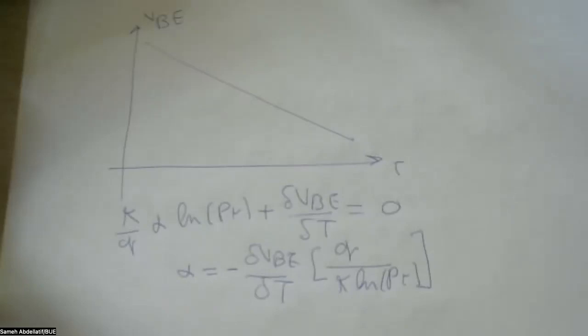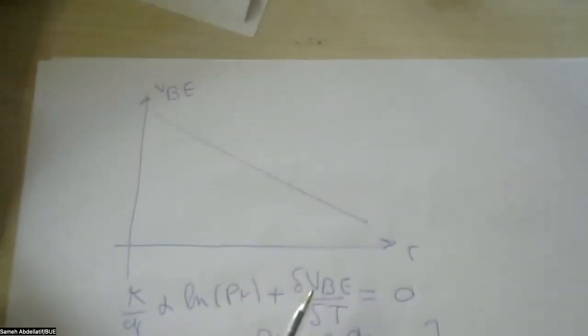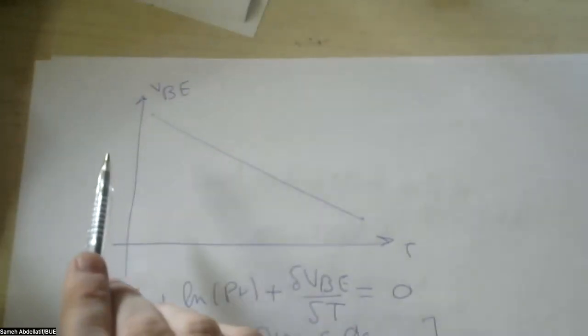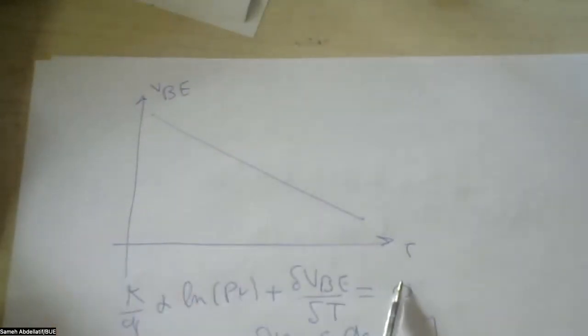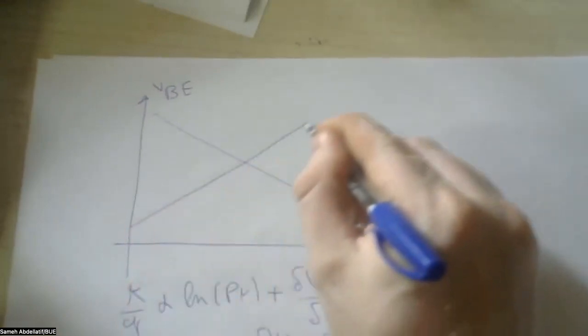So you now intend to have alpha, which is still temperature dependent. Instead of having alpha a constant, it will now turn into a temperature dependent parameter. But its temperature dependence is typically the reverse with respect to the VBE dependence. So if you have a VBE dependence with respect to temperature in this manner, then you will have a reverse manner, looking like that.